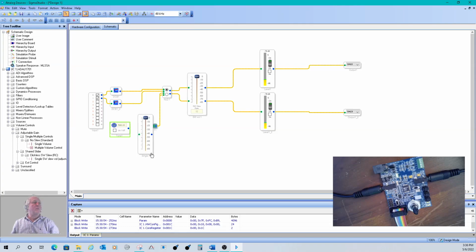I don't care if it has a little bit of zipper noise, because these oscillators, the signal sources, are at 0 dB FS for a 24-bit signal. It's max volume to go out to serial ports, so you want to be careful with that. It could hurt things. I'm going to hook it up, turn it on, and turn it down about 30 dB because I don't want the tone that loud. And let's link, compile, download.